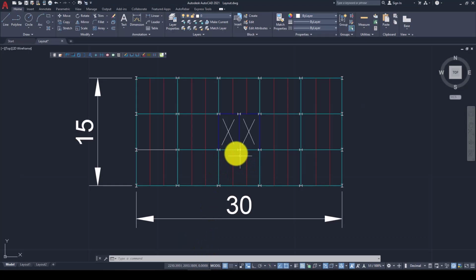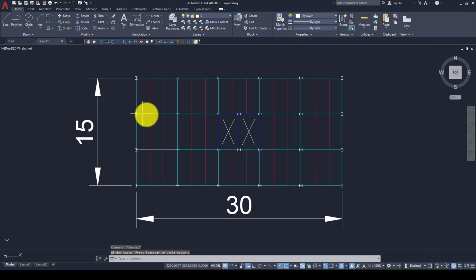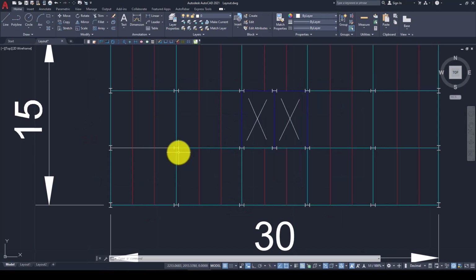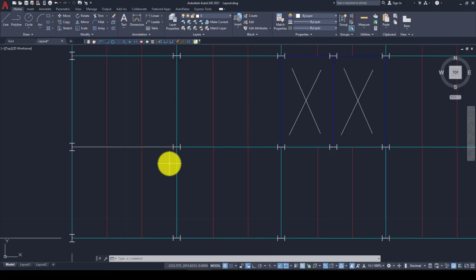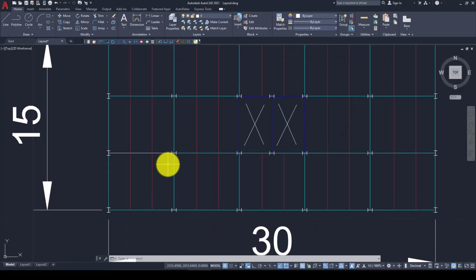Let me show the plan of the structure we intend to model, analyze and design. So this is the structure. This is a typical steel concentrically braced frame. We have a core steel bracing in the center of the structure, and the perimeter in the other part is still a moment resisting structure. Moment resisting structure means that we're not adding any moment releases here. The connection is quite rigid and fixed.